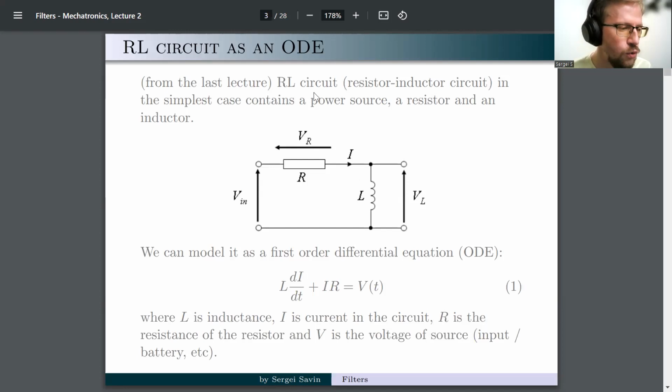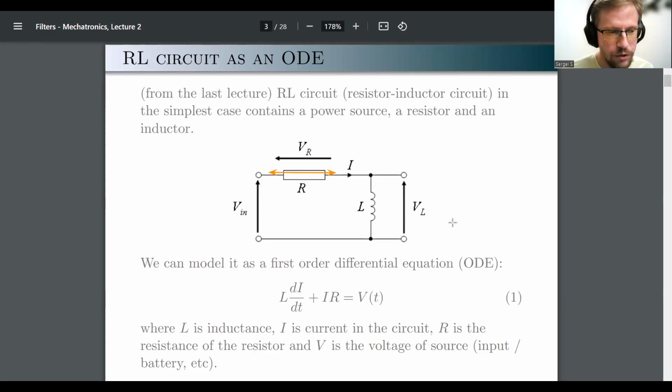And if you measure your voltage across a resistor here, you're going to see exactly the same picture, multiplied by R. So at high frequencies, everything tends to 0. At low frequencies, everything tends to 1, right? 1 over R times R is 1. That is quite interesting. You would see an amplitude gain of 1 on low frequencies. Somehow again it makes sense, right? The entire voltage that passes in is going to be dissipated on the resistor. So this is why the gain is 1.